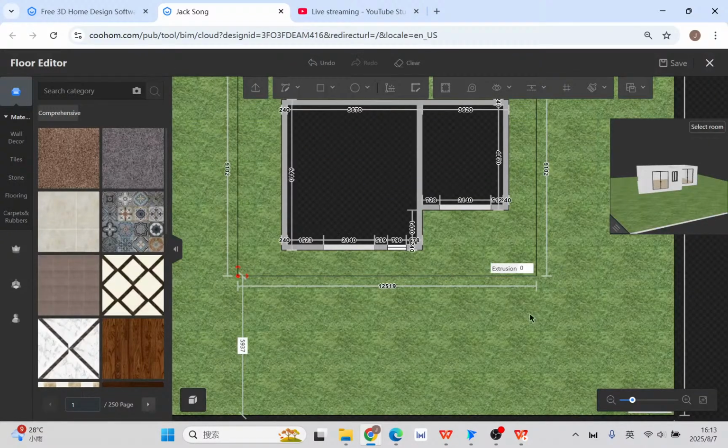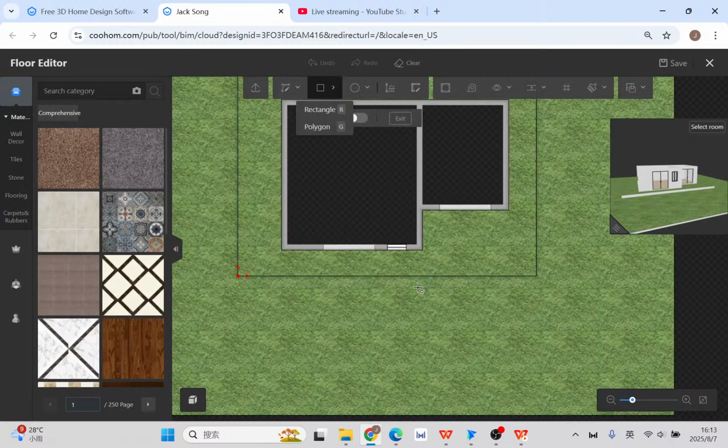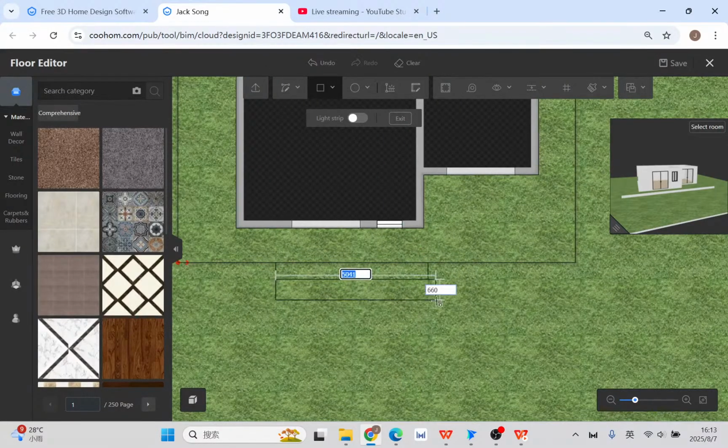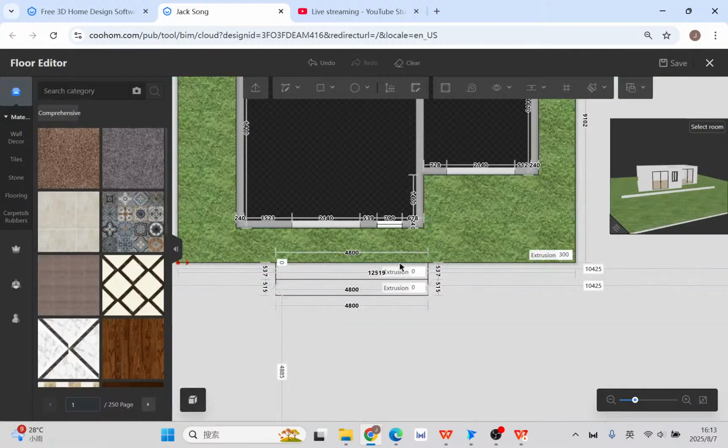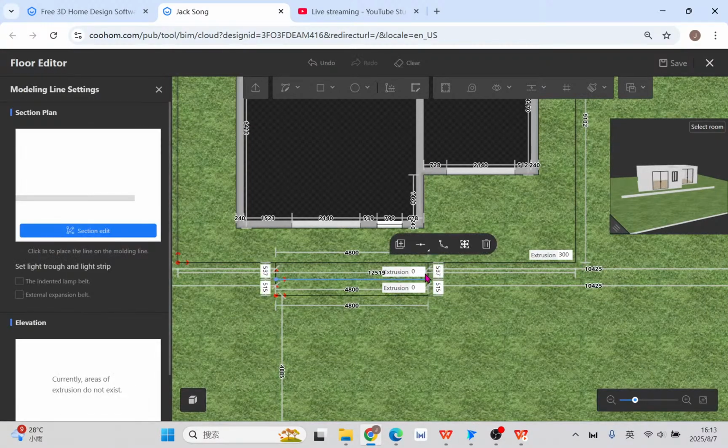Okay, drop changing. Let's say here it's flat, so we can still draw with the rectangle. Assuming extrusion is still 300, it is still flat. Then continually, for example, you can turn to another level. Set a different extrusion for the drop as the stairs, for example 150.